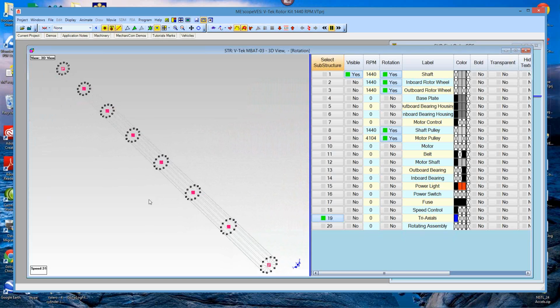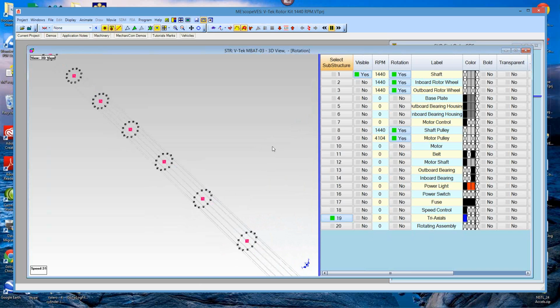Now the center point is going to animate based on the data from the two bearing block accelerometers, and then the radial points, what we call radial points, rotating around each center point, are going to animate based on the motion of their center point. And we'll use interpolation to do that. So let me just show you very quickly how we would set that kind of thing up.